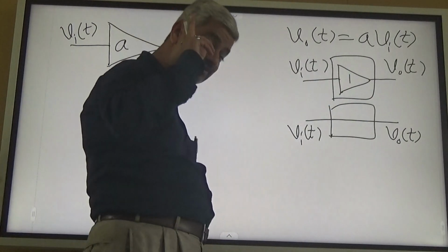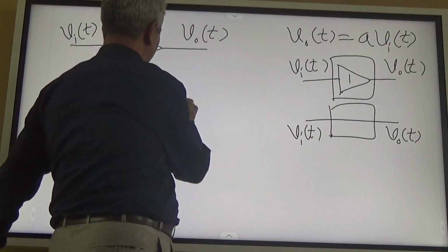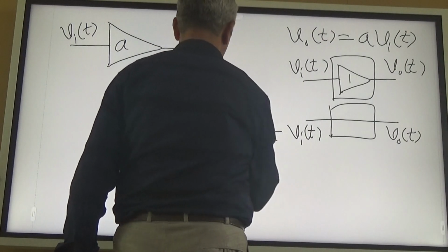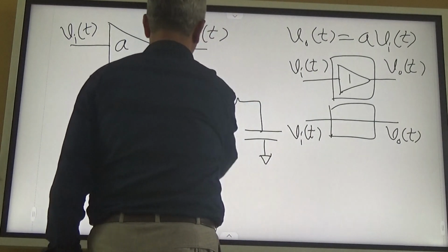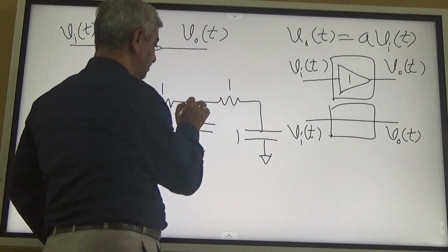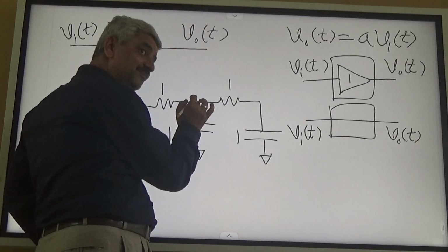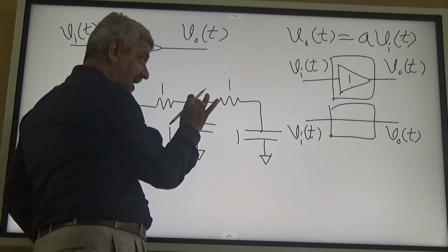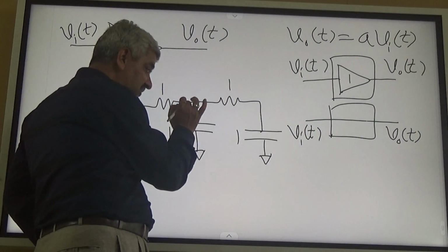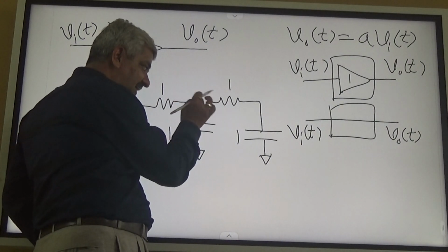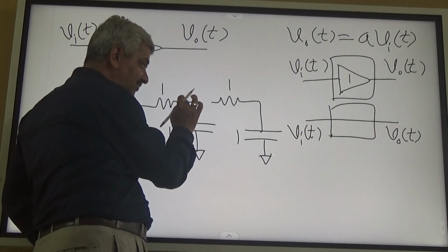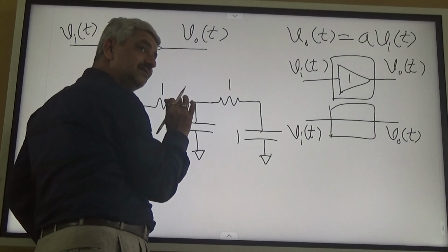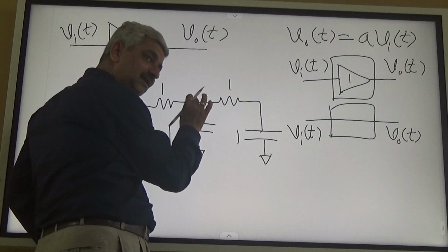This is most important, because these two are different circuits now. This is the first circuit which we discussed in the classroom. When I connect this here, it draws current, so Kirchhoff's node law applies here. When it is not connected, current is flowing through this entire path. When I connect this, Kirchhoff's node law gets applied and current is diverted.